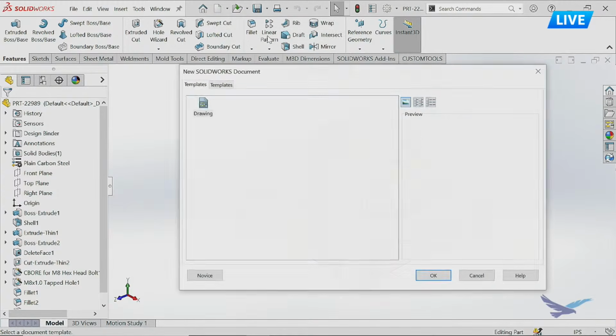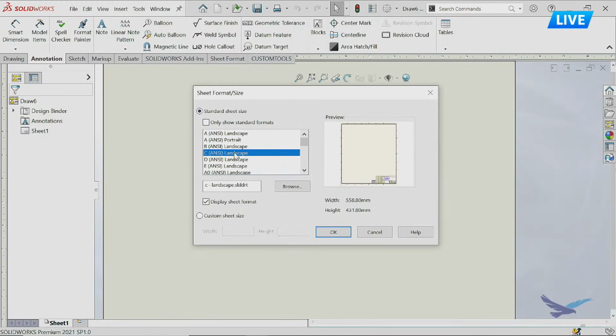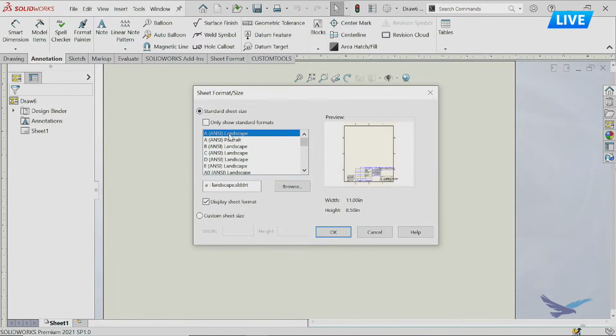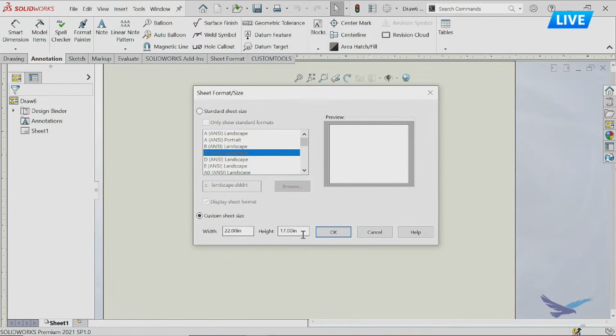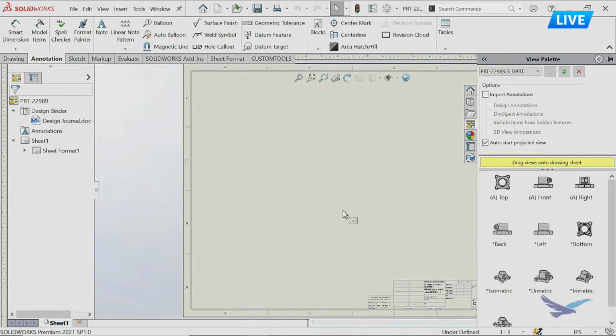So when I develop templates, I prefer to use a part inside the drawing. That helps me understand if the links are working or not and saves me iterations modifying that template. So let me go ahead and create a new drawing. Like I said, I'm gonna use one of the stock templates. So if you have SOLIDWORKS, you have this default template on your system. This template does not have an associative sheet format. So SOLIDWORKS prompts me to select one. And selecting the sheet format dictates the title block and the sheet size. Now it is possible to start with a blank one, but in today's example, I'm gonna start with an existing one to kind of speed up the process for you.